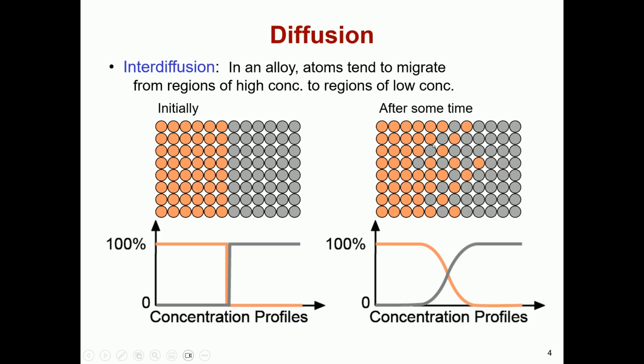The high concentration side becomes diluted, while the low concentration side becomes enriched. Given sufficient time, the system reaches equilibrium with uniform composition throughout; they become half and half. However, this only occurs when the elements can form a solid solution, when they are similar enough to mix. If the elements are incompatible, for example if one is much larger than the other, sharp interfaces will remain instead.